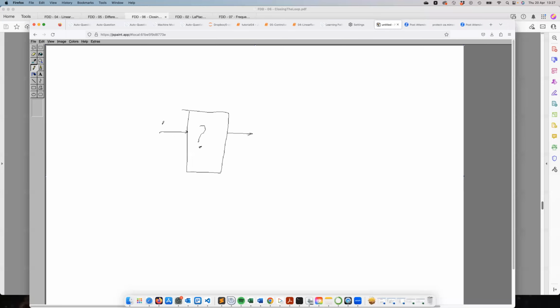And so we want to put some signal in here, and we want to measure some output out here. And we want to try to interpret the response that we get, right? So we'll get some output here in response to our input there. And we are hoping that we can interpret that to give us this function g. And remember, again, g we got from deriving the process. So maybe go back and have a look at that 2 tanks case.